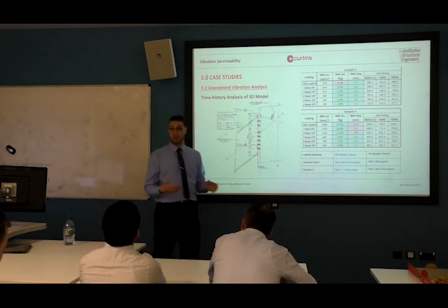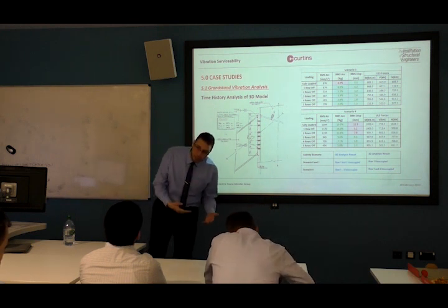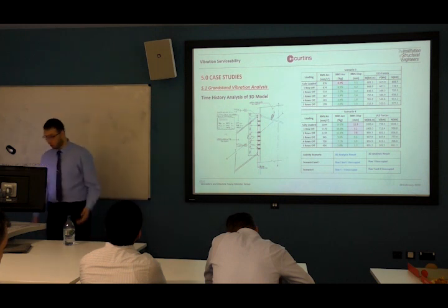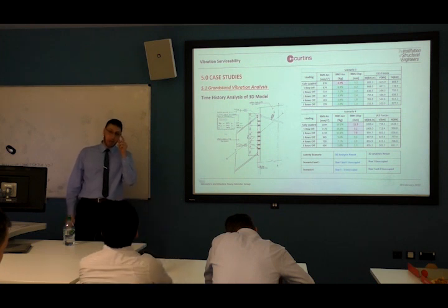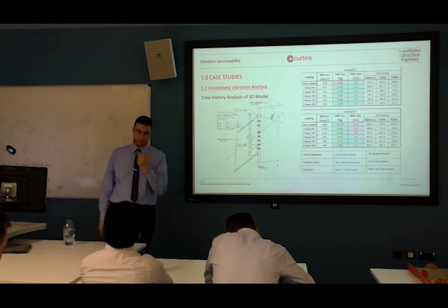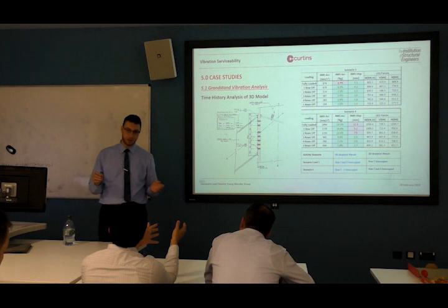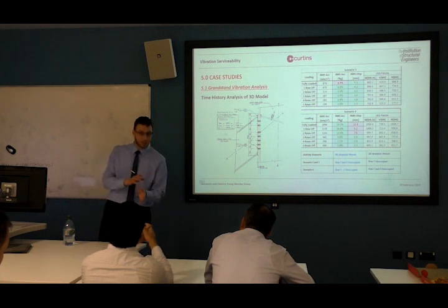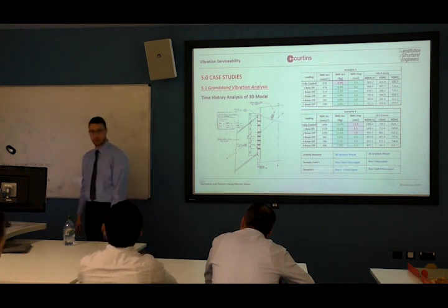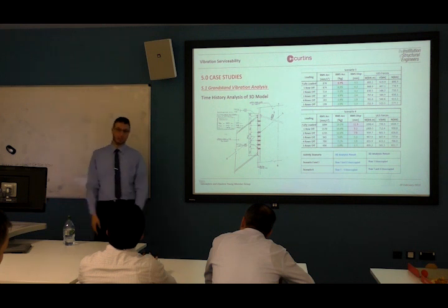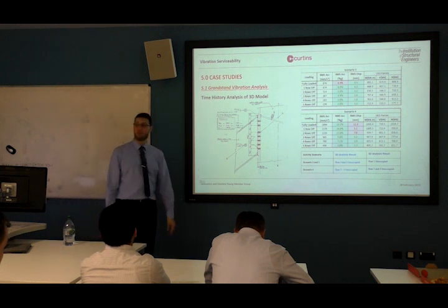If it's pinned and you model it as rigid, then you are not representing the structure as it's behaving. So you're right, sometimes. In fact, they all suggest that you just model it as rigid, even if it's pinned. It depends. It's correct to a limit. It depends on the load. Yes, thank you so much. Again, engineering judgment in this case. All right. So this is how we solve this grandstand.